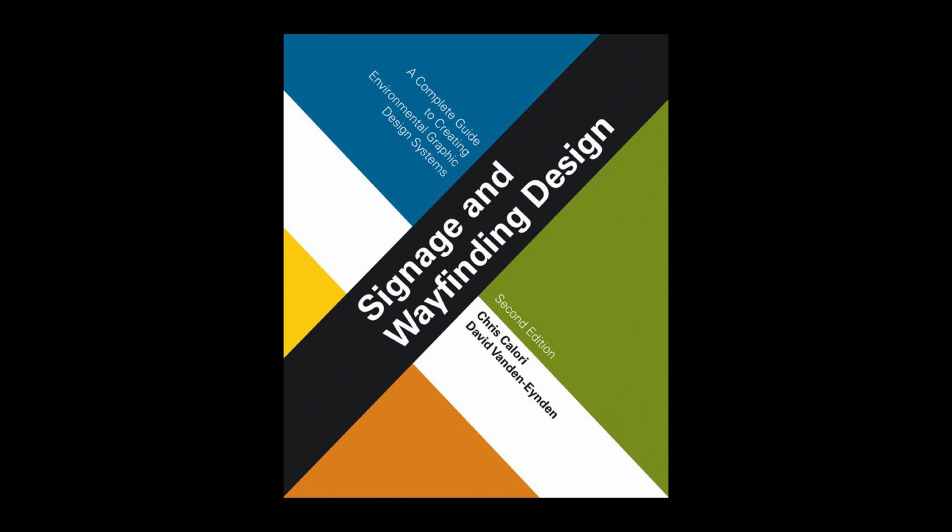This alarms some clients, however, because they think that there's too many signs or that the signs are going to be really large or that they're too close together, so some explanation of the scale discrepancy may be necessary. There are projects where indicating the signs in scale on the plan is useful and necessary. In some cases, the base plans must be of adequate scale so the signs can be accurately indicated and seen in the same scale, which may result in several plan sheets with match lines for a given area.